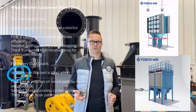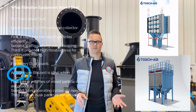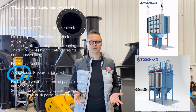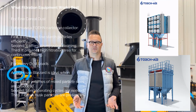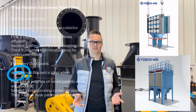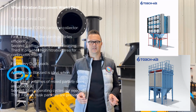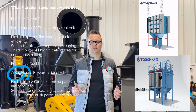What filtration equipment works best for fine cereal dust? I often use a pleated cartridge collector. First, it captures fine starch particles efficiently. Second, it offers strong pulse cleaning. Third, it provides high filtration area for continuous milling with heavy dust loads. A baghouse is ideal when, first, large volumes of mixed particle sizes are produced. Second, long operating cycles are needed. Third, fibrous husk particles are present.